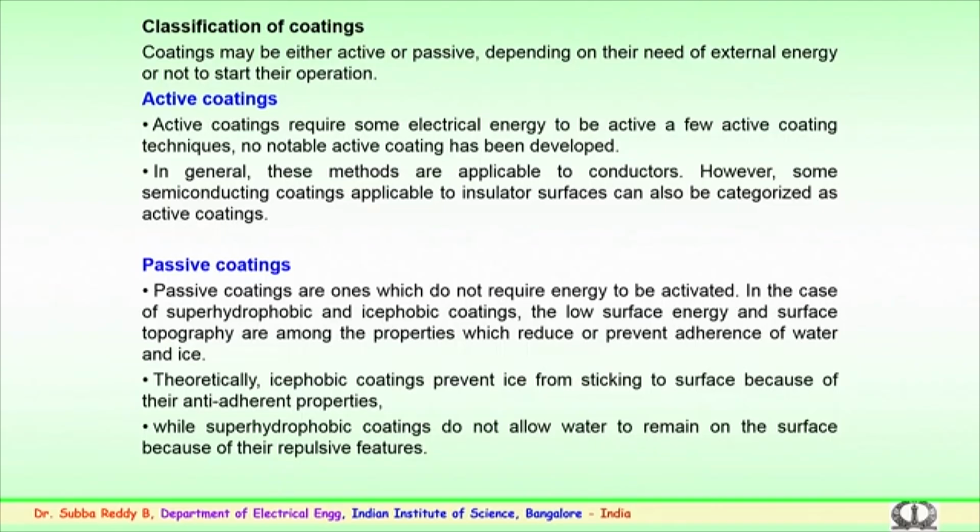Passive coatings, as mentioned earlier, are the ones which do not require energy to be activated. In the case of super hydrophobic and icephobic coatings, low surface energy and surface topography are among the properties which reduce or prevent adherence of water and ice on the surfaces. So, theoretically icephobic coatings prevent ice from sticking to the surfaces. This is the important point for passive coatings.